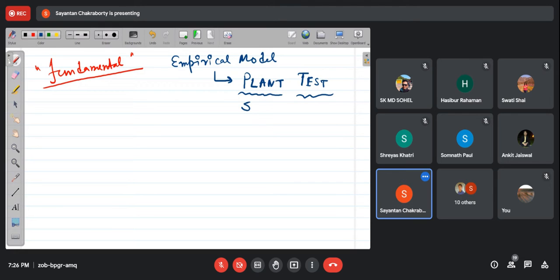That is a step change in the manipulated variable. That is nothing but the controller output, and then we observe the process output, how the process output reacts to this step change in the manipulated variable, right? And from that response, we obtain or develop the best match between the model output and the observed plant output via some empirical equations.